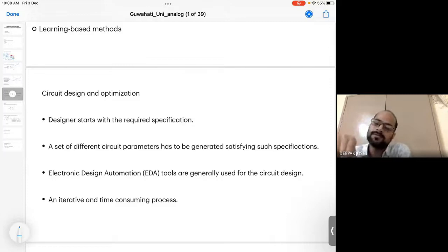The lower NMOS can have its body directly connected to the ground, but not the upper one. In the upper one, you will have to consider the body effect. Now the mathematical expressions you use manually, the relations of gm and the square law, change, so you have to take the body effect into account.